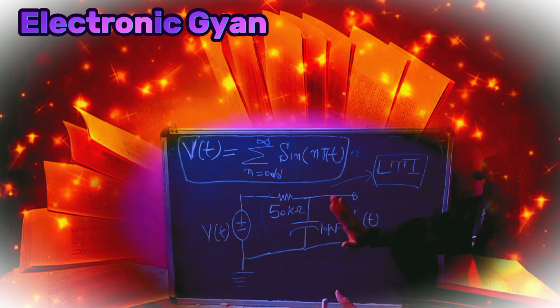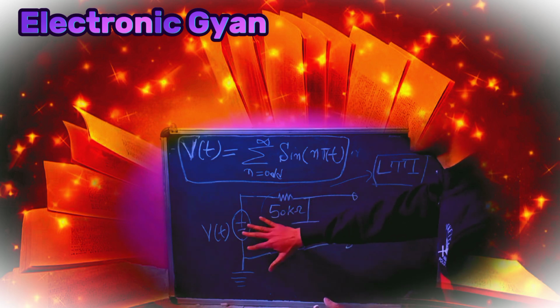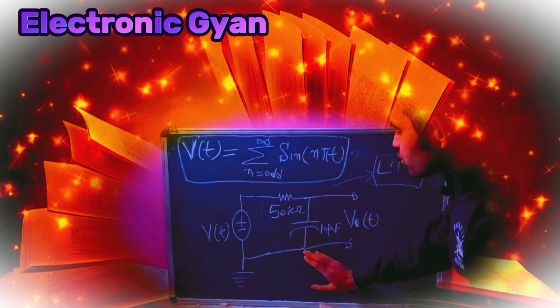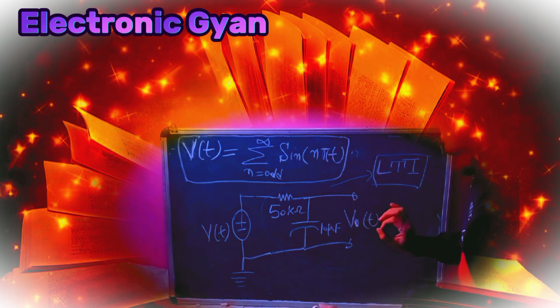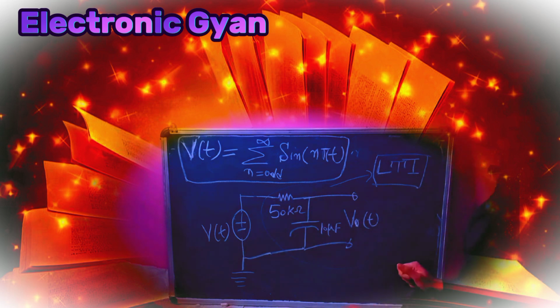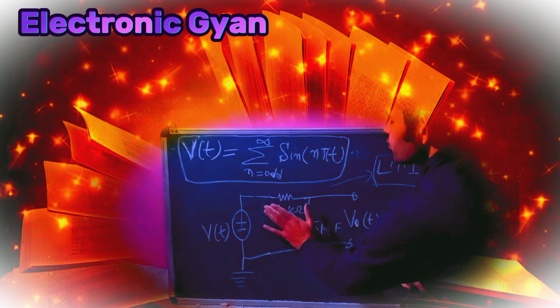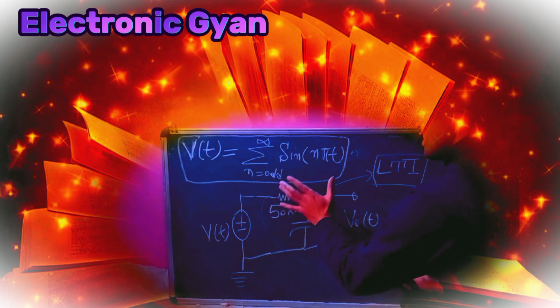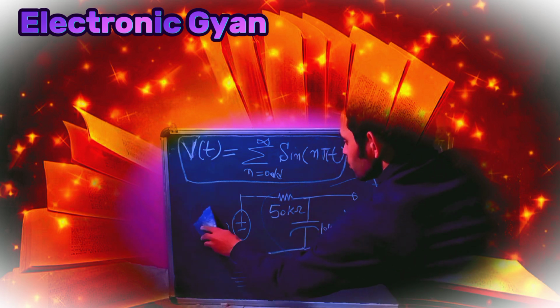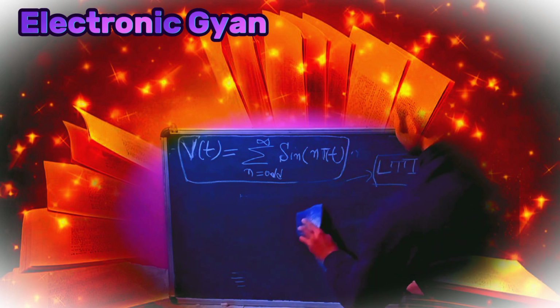Yes, that we know very well, that for any LTI system, if my input is sinusoidal, then my steady state output will also be sinusoidal with the same frequency, but the amplitude and phase may vary. Now first of all we are going to find its transfer function. From the transfer function we will calculate the magnitude response and phase response for this frequency. So let's see how to calculate that.